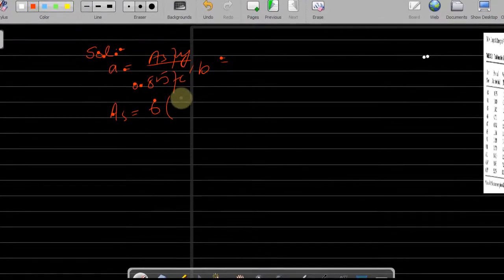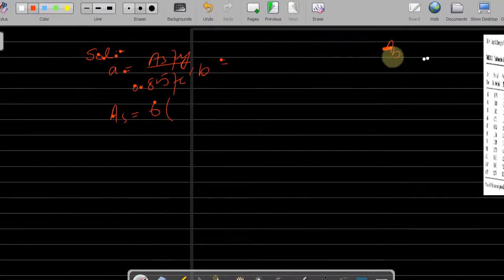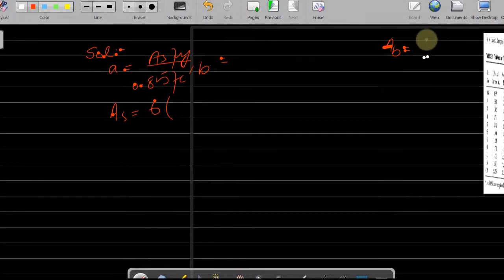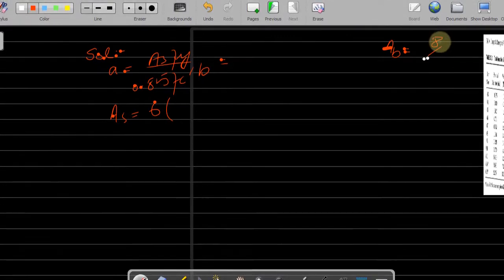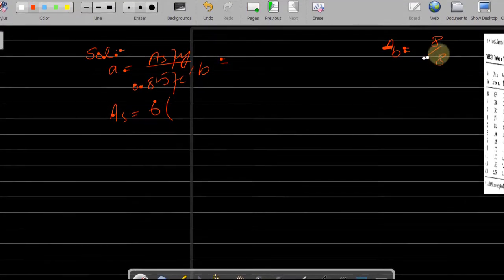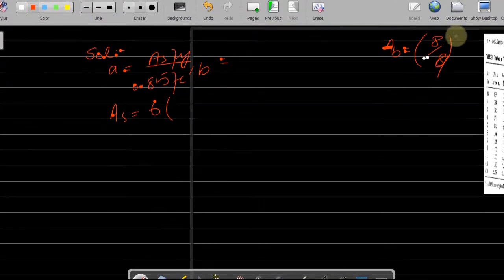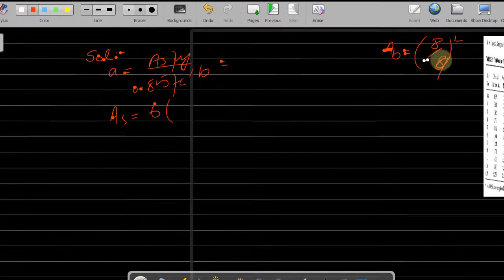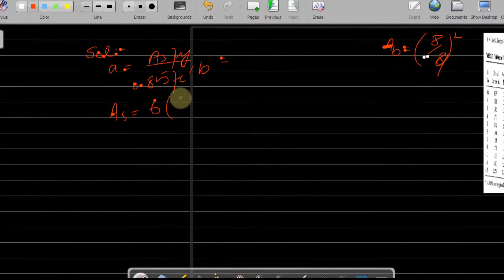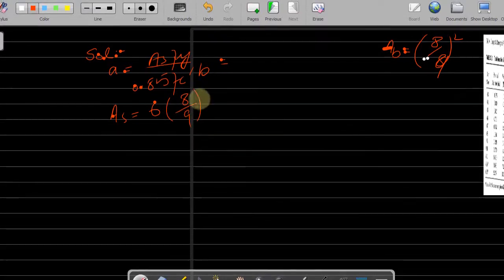If you want to calculate the area of steel, that is Ab, of any bar, you have an easy formula: the number of bar divided by 8, squared. It will give you the area of that bar. Number of bar divided by 8 squared. So we are using number 8 bar, so number 8 divided by 8 squared.